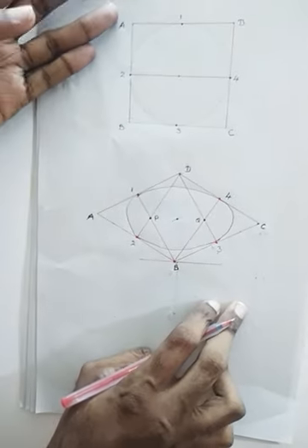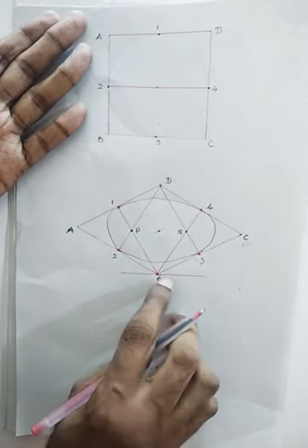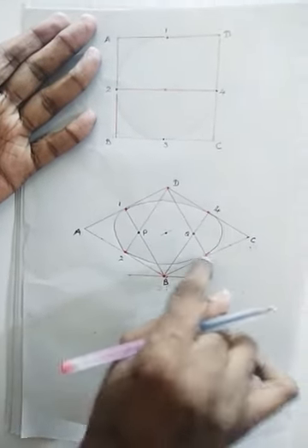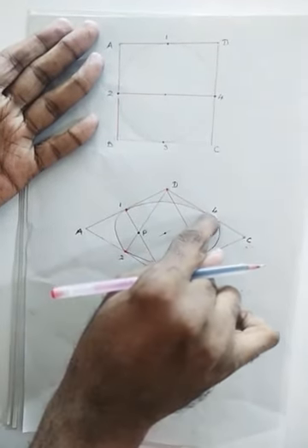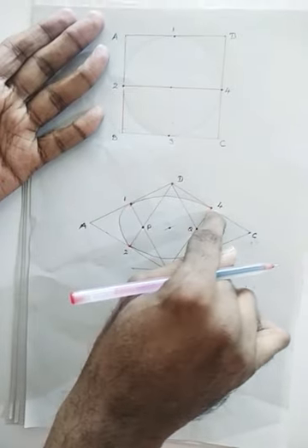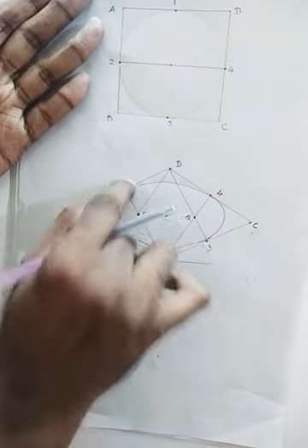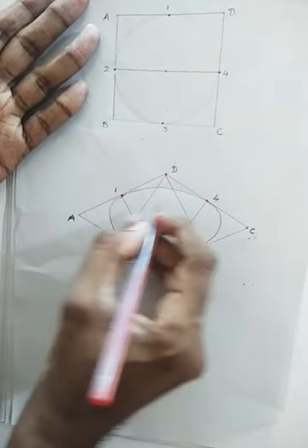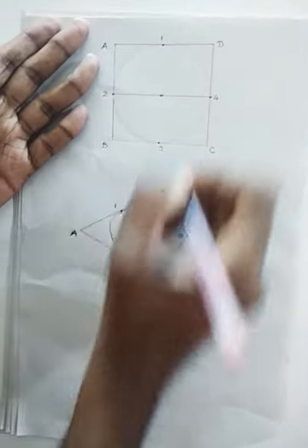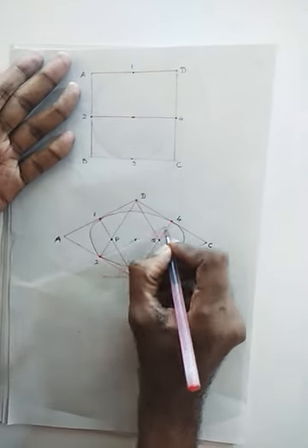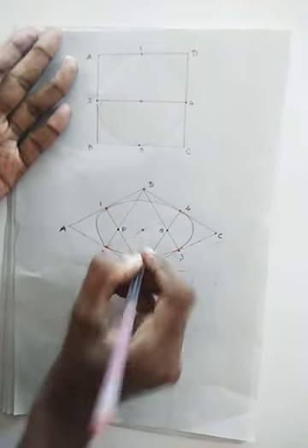So we will be drawing the ellipse using our compass itself. First, D as center, D2 radius, I will be drawing an arc. Next, Q as center, Q3 radius, I will be drawing an arc. Next, B as center, B4 radius, I will be drawing an arc. And last, P as center, P1 as radius, I will be drawing an arc. Next, I have to find the center of this ellipse. For that, you can see if I join 2 and 4, it will pass exactly through the center. Here also, you draw a light line joining 2 and 4, and you transfer this distance, we will be getting the center.